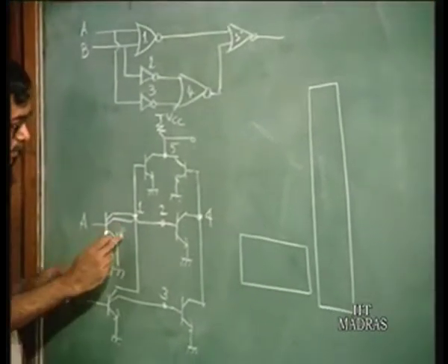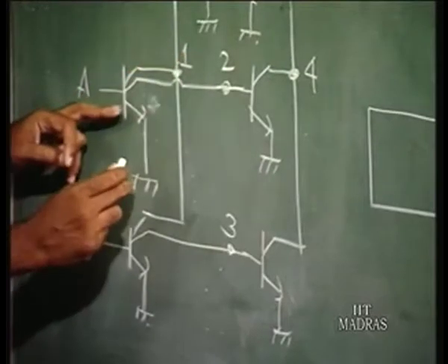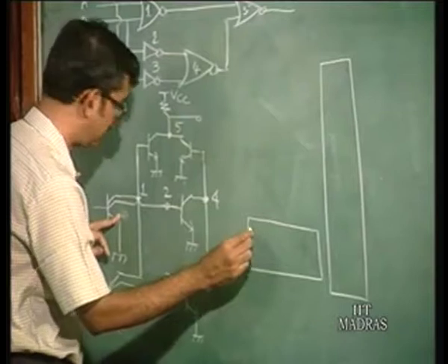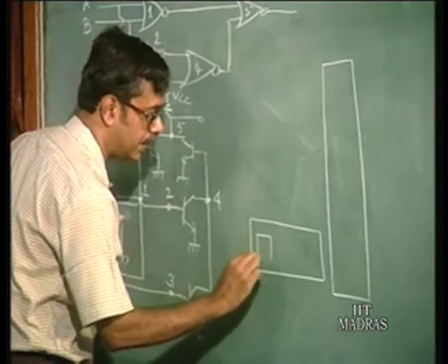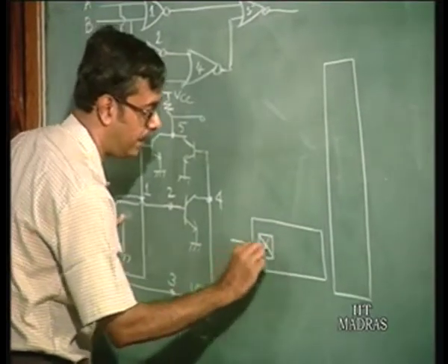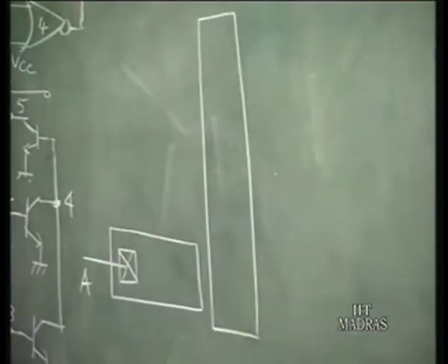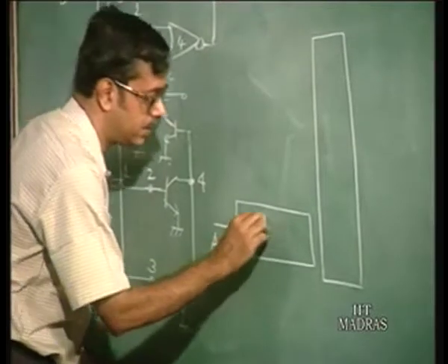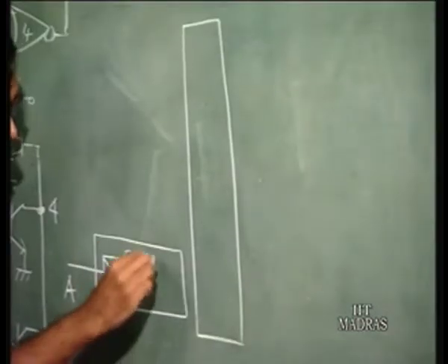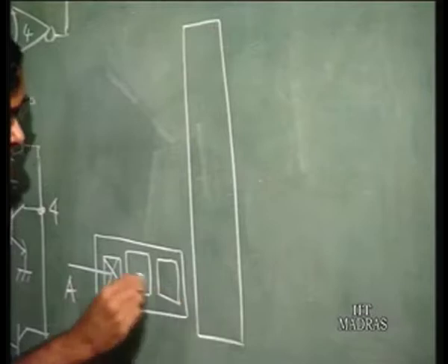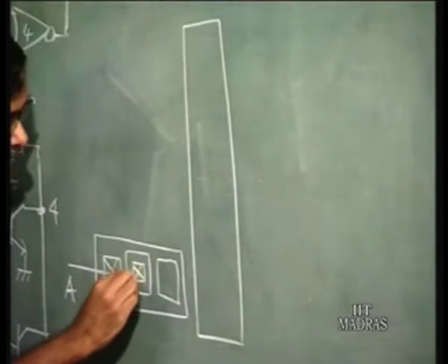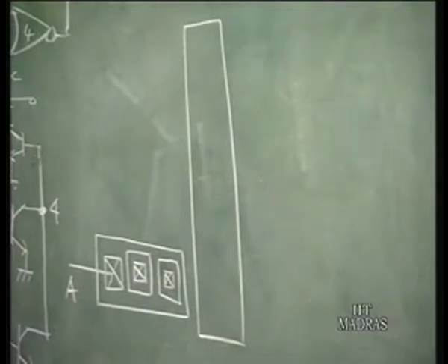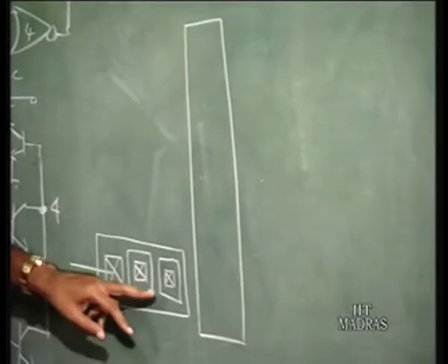Okay, I think it's going to be confusing, but anyway, this is already 1, 2, 3, 4 on the board. So anyway, if you consider this to be the first transistor, at the base of which you have the input A, this has 2 collectors. All right, this particular transistor has 2 collectors. So collectors, you know, are drawn like this, the layout. Then this is the contact for the collectors. So this is one cell. All right, one base, 2 collectors.